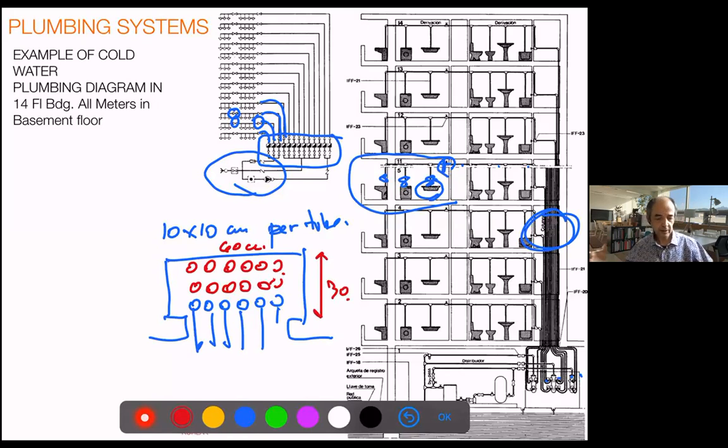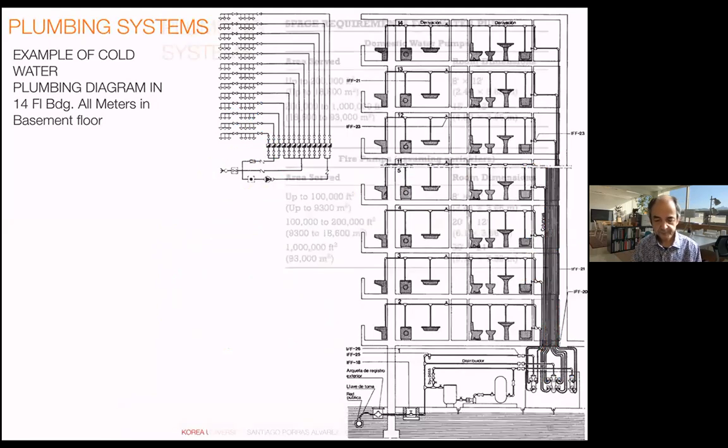If the units are larger hotels, you may need a different dimensioning, right? So in vertical, as you see, you will have each pipe just appearing on the front of the shaft, so you can just inspect or repair from that inspection wall.